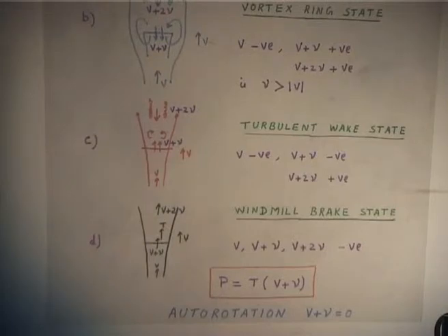But actually you will find in real situations autorotation is a little different, that we will learn, because this you have to know. That means I do not require power to support my weight, but that does not mean that I am hovering, please understand, I am coming down. So, the loss of potential energy is actually converted into the kinetic energy in spinning. Suppose if more is converted, it will start spinning faster. You do not want that situation.